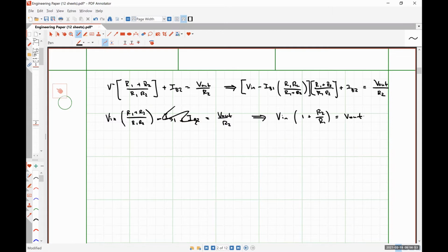So putting that particular resistance, R1 in parallel with R2, completely negates the effects of the bias currents while maintaining the transfer relationship of our circuit. So that's a pretty insightful thing.